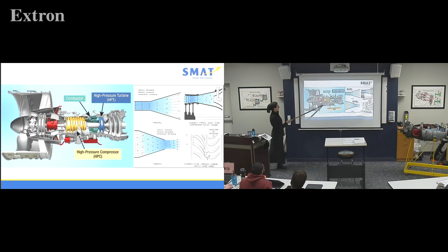Some bypassing, and some going to, what are these? And specifically, what's the difference between these ones and these ones? Excellent. Low pressure compressor, high pressure compressor. It's hard to say. And you can see it's nicely labeled. Our high pressure compressor goes to our high pressure turbine, low pressure compressor, and if it's just dual, not triple spool, the fan is on the same spool as the low pressure compressor going through in between to the low pressure turbine.